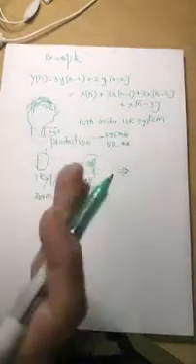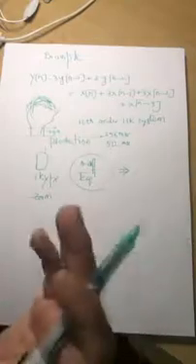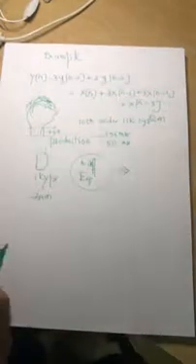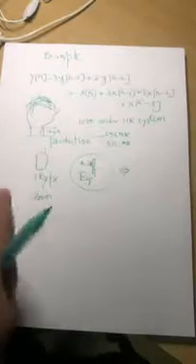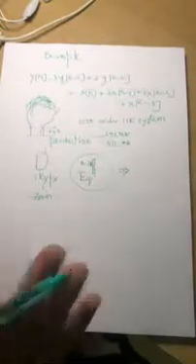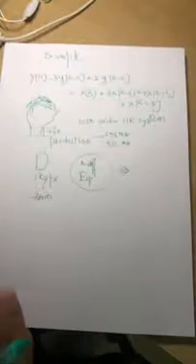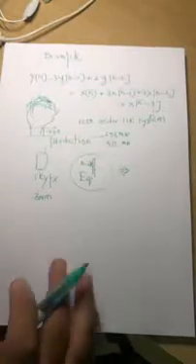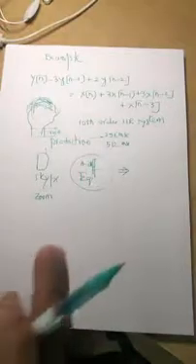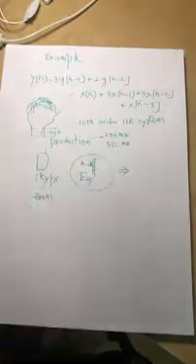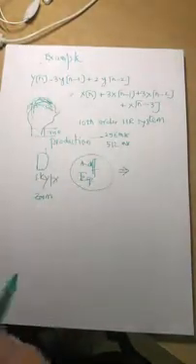Speech is modeled as a 10th order system, almost the same as what we did, where you are only finding coefficient A. For speech, they have to find 10 coefficients, A1, A2, A3, A4, and so on, and it's an all-pole system, with no zeros. Once you have the system, you check its stability. If it is stable, then you transmit. So checking stability is very important.